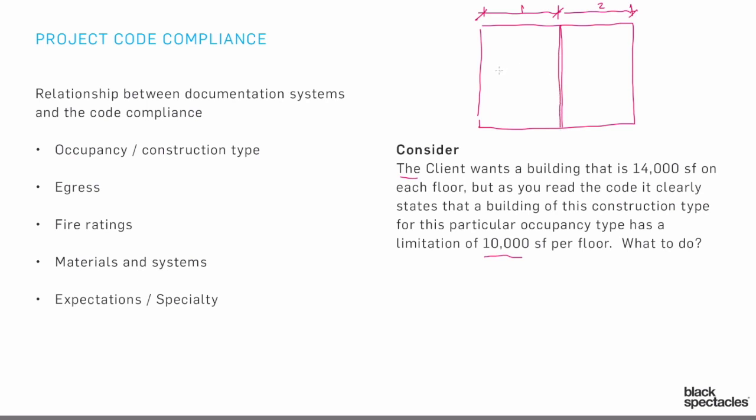And then if my corridor goes right across from one side to the other, I would be able to have doors at this point, but I could just leave those doors open on some sort of hold-open element, like a magnetic system that's part of the alarm system, so that when the alarm goes off, those doors would close and make the continuation of that 4-hour wall.